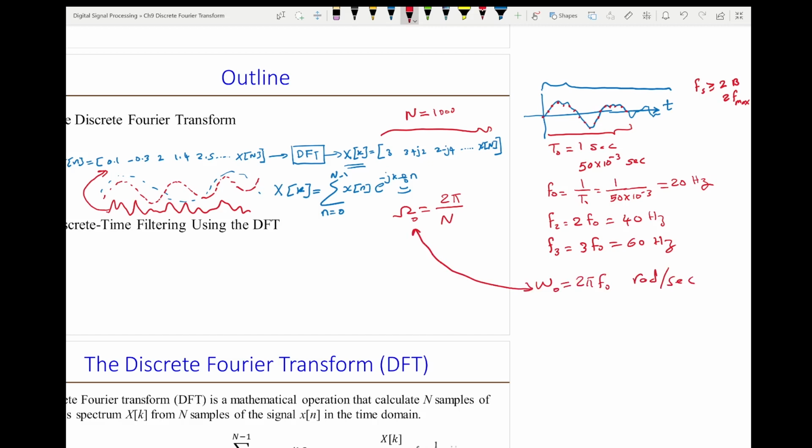Well, if we start with a signal in the time domain, continuous, x of t is cosine omega 0 t, and then we want to convert it to a discrete x of n, cosine omega 0. Now t will equal n capital T, where capital T is the sampling interval, which is the same as n divided by f of s. T, remember, is 1 over f of s.